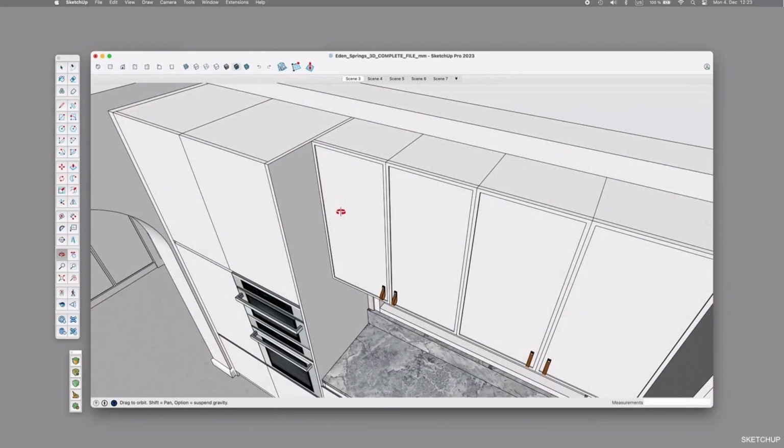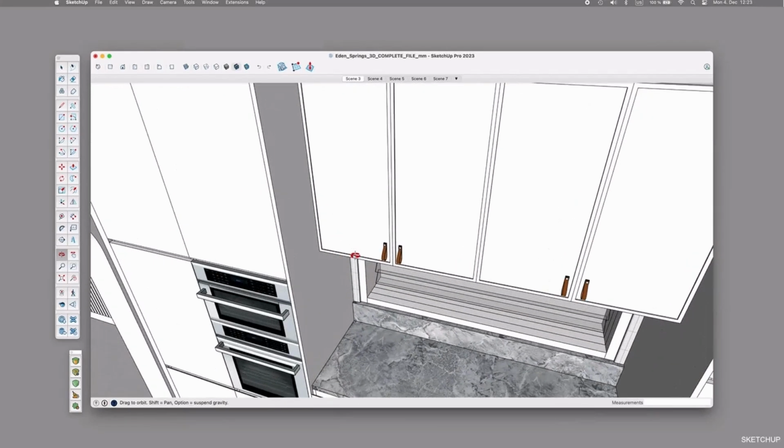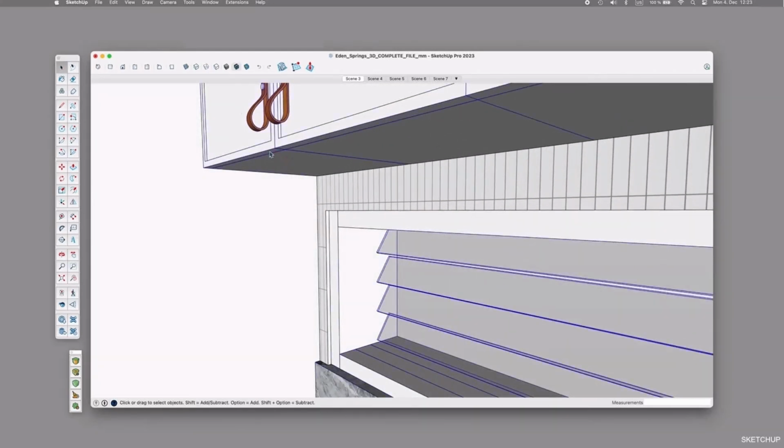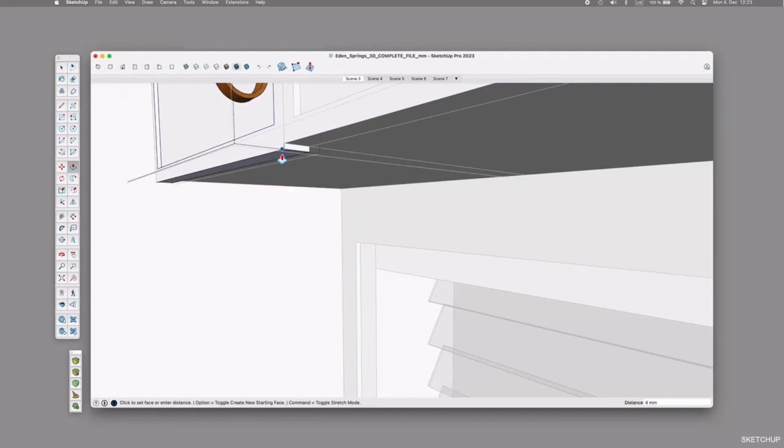A nice tip I can give if you would like to use very basic kitchen fronts and do not want any handles or a push-open mechanism, consider a 5 mm front door overhang, creating a finger pull right there. It's a very affordable alternative and it's functional.